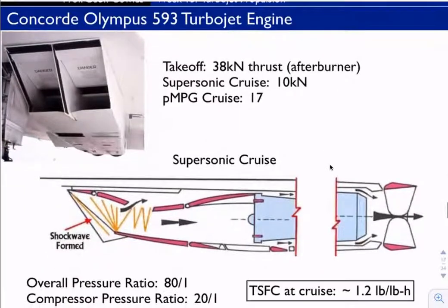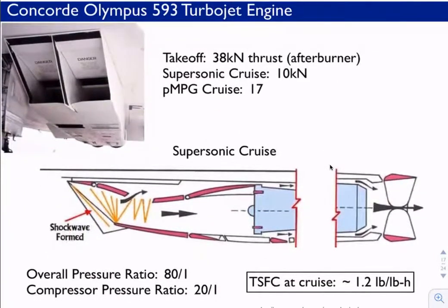The Concorde is another example of that, a jet engine that was flying supercruise at Mach 2 plus for hours on end, but also had to take off and produce maximum thrust at takeoff. And there they have these ducts. These are the intake ducts of the engines under each wing. They were able to manipulate the geometry of these intake ducts to create the shock waves when needed.